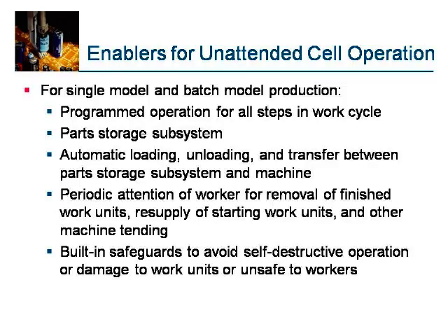Enablers for unattended cell operation for mixed model production: all of the preceding enablers plus work unit identification, automatic identification, sensors that recognize alternative features of starting units. If starting units are the same, work unit identification is unnecessary. Capability to download programs for each work unit style.